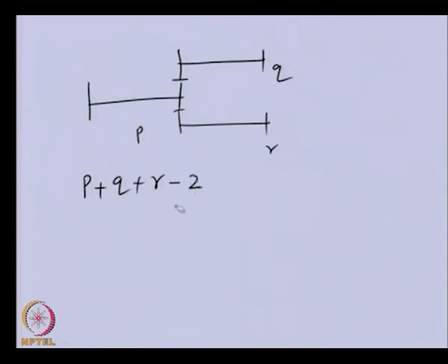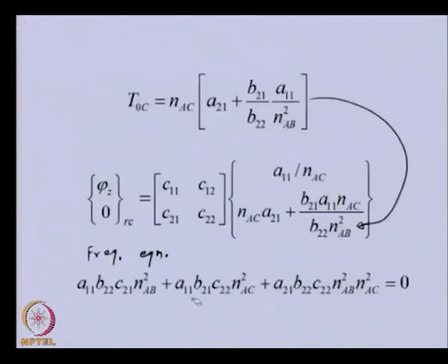So, these many natural frequencies we expect from the previous frequency equation, and once we get the frequency equation, we can use transfer matrices to get the relative displacements at various locations to get the mode shapes corresponding to each of the natural frequencies. Let us take one example of a branch system in which whatever method we explained will be more clear.